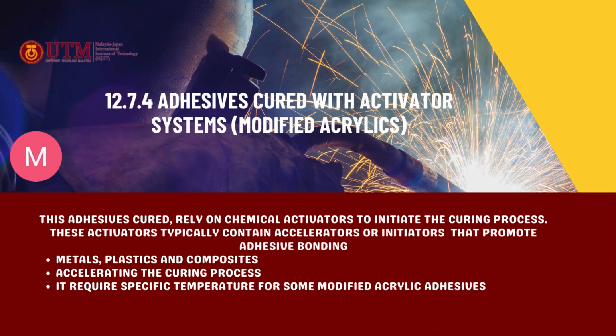For activator system modified acrylics, this adhesive cure relies on chemical activators to initiate the curing process. These activators typically contain accelerators or initiators that promote adhesive bonding. It bonds metals, plastic, and composites. It accelerates the curing process and requires a specific temperature for some modified acrylic adhesives.